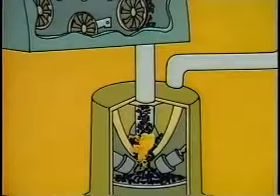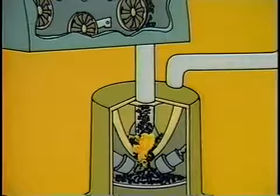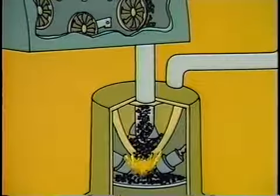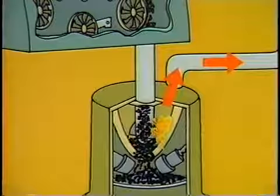As with the other equipment fires we've discussed, the primary method of handling a pulverizer fire is to increase the flow of coal through the pulverizer. This gets the coal out of the pulverizer and to the burners as rapidly as possible.